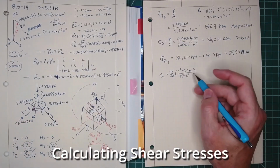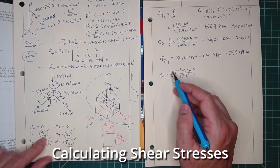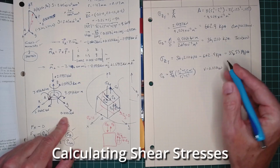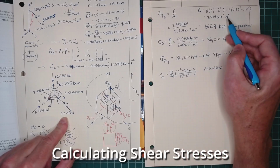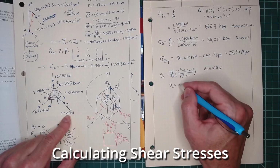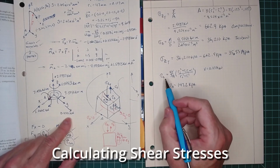Now, we know the shear. Remember the shear, we can come back over here. This is in the y direction. So our V in this case is going to be equal to 0.3331 kilonewtons. We plug this in here. We calculated our area before, and it's in our standard meter notation. So we can plug everything in, and once we do that, we end up with 147.2 kilopascals for tau B.